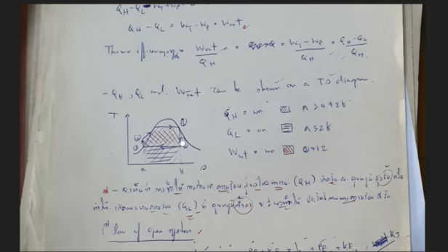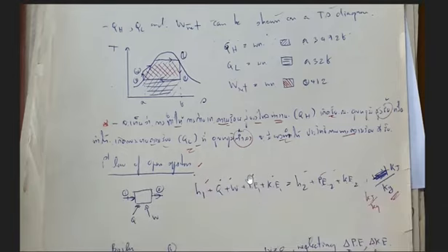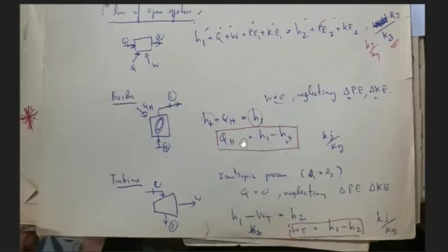but an actual turbine is not ideal. The entropy will increase a little bit, so point 2 might be somewhere around here. But anyway, we can measure. If we know the temperature and the pressure, we can determine the entropy. So we can find the entropy and use it in the formula anyway.